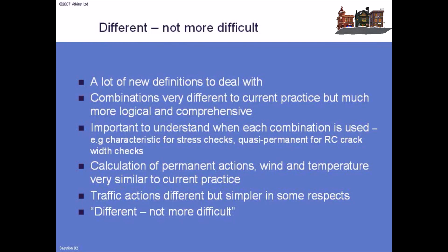So I mean, most of the load calculation is very similar to what we did before. The traffic is very different, but again, with a bit of practice, it's actually quite simple in many ways. It's actually simpler to apply to the structure. And with that sort of patch loading, you can, in many situations, go back to just eyeing up where to put the load on a structure rather than having to generate lots of influence lines to precisely calculate the loaded length. So it's quite a lot of positives there.